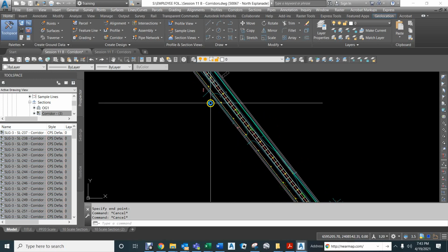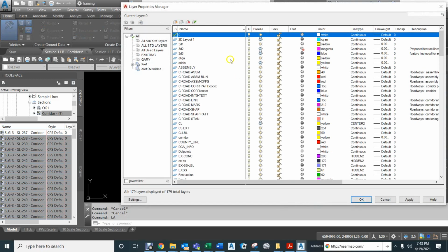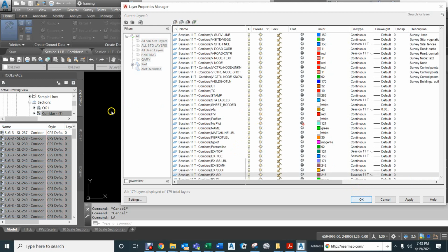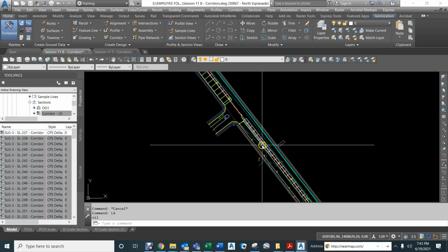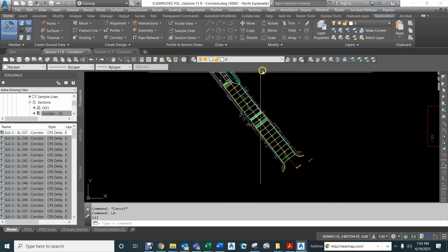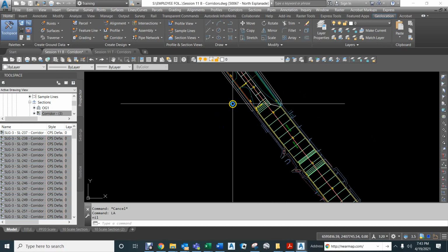We're going to have to put some drainages in there, but instead of freezing everything or thawing everything, let me go to the layer command here, and I'm going to look at all the frozen, and we'll use X storm drain manhole, and X storm drain. We'll turn those two things on, and that will show us the existing facilities, and then we can go from there. So in this area of the roadway, it doesn't look like we have a lot of drainage features.